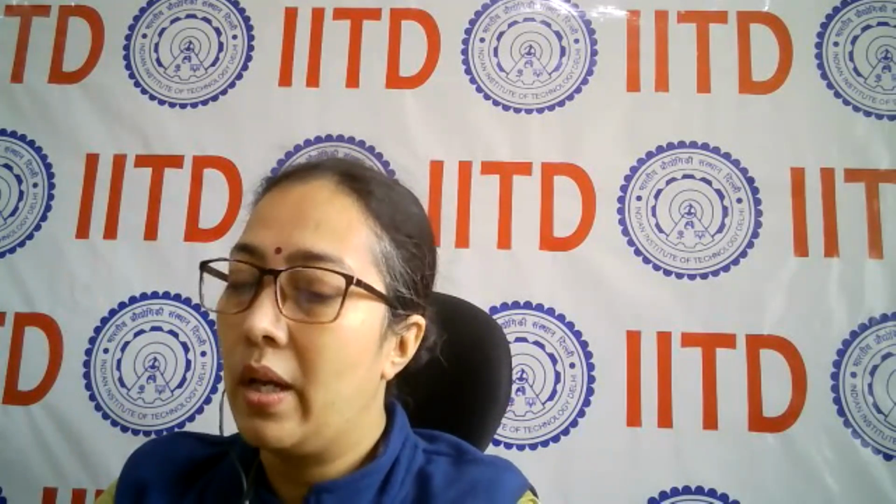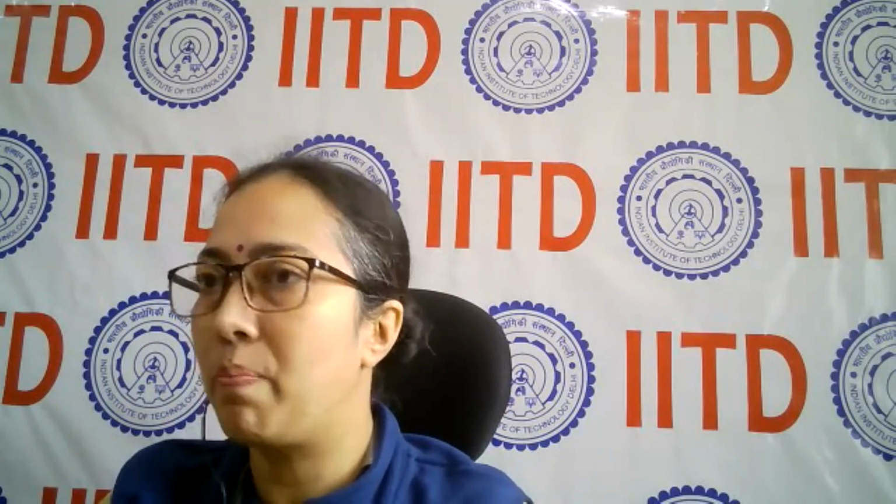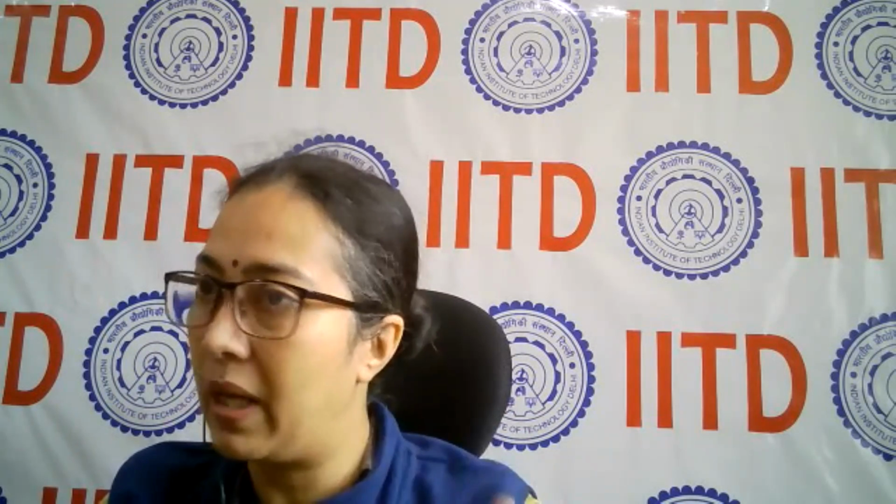And I also told you that it depends upon the meteorological region where you are. Canada gets a lot of benefit from hydro power. Their emissions are very little. One, because they have very big capacity hydropower projects. And second, because they are a relatively cold country, the emission and the vegetation growth in their dam is very little. The same hydropower plant, if I bring it to India, or take it to other tropical countries, the emissions would be much higher. I'm just talking about the dam at the moment, not the water that flows down and produces electricity. The dam itself. So the tipping point that could take hydropower to the green side or put it on the emitting side is the dam: how you are operating the dam, how much water you are holding, how much concrete has gone into making that dam also.